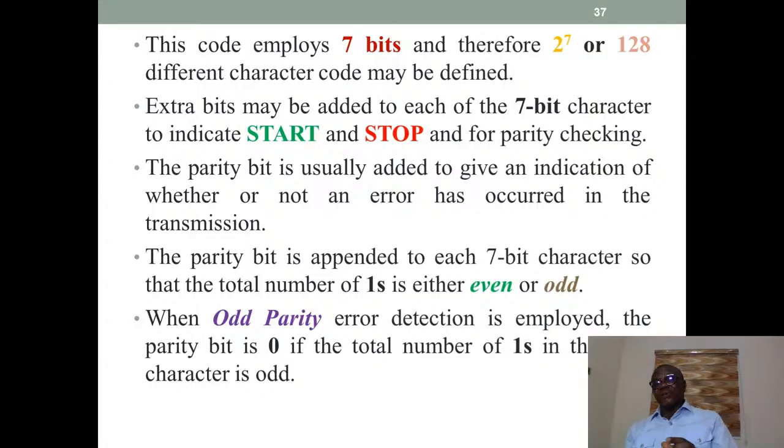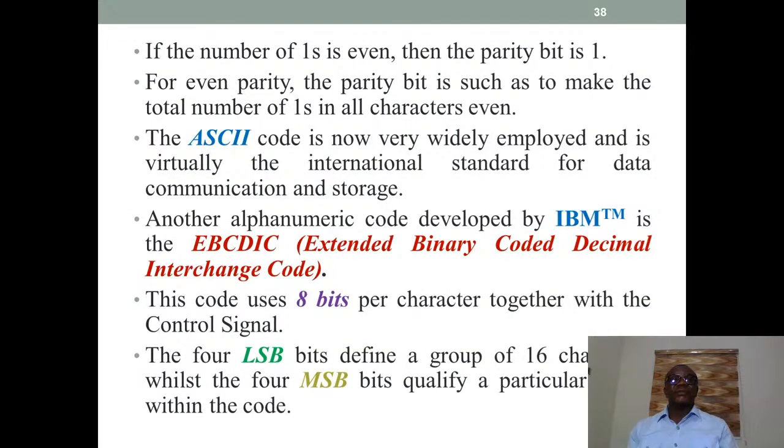We will see how the system can detect the bit that is in error, using this parity check, and correct it. Because if it detects that the bit in error is a 0, on its own it changes it to 1, and by the time it changes it to 1, it becomes correct. So your system is able to do error detection and correction.